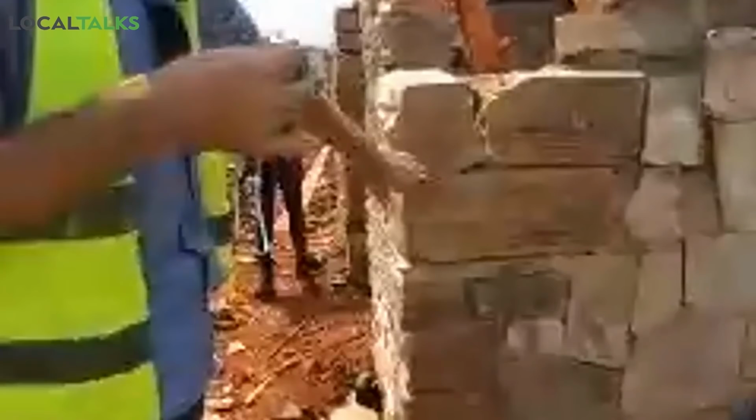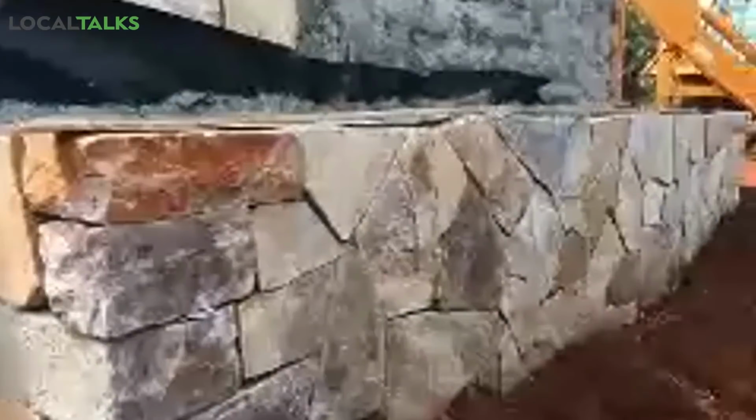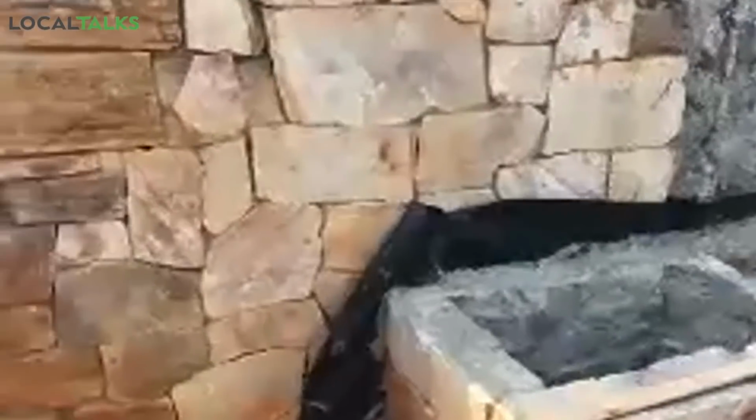And what we are trying to do here is use this building to learn our preferred way, for this project, of dealing with the stone. We developed this idea of using big block slates in the corners, and then transitioning into the wall, where we are joining normal thin slates. We quite like that look, the strong look it gives to the corners, really showing that this is actually a stone wall and not just a clad wall that has a problem in the corners where the two slates don't know what to do.